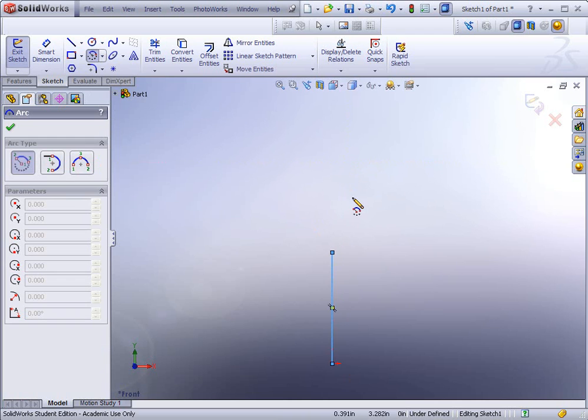The first thing you have to locate, in this case I've zoomed out, and you could even pan your screen down a little bit because you have to give yourself some room up above it. And we just go ahead and glide up above our line, maybe about 1.5 inches or so, and then we click once we infer to the center. And we drag, and then we click again on the vertex of the line that we drew just a moment ago.